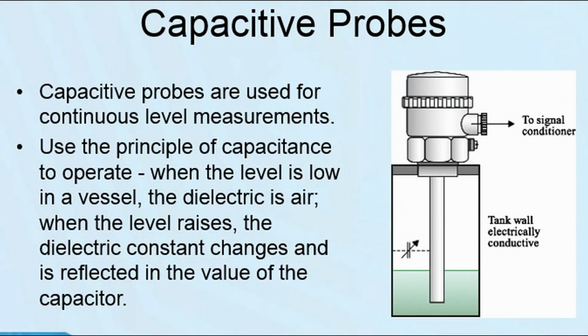A capacitive sensor works because the liquid that's being measured is also considered a dielectric, and if you have more liquid, then the dielectric is more and the capacitance goes up, and this gives an indication of the level. The capacitive sensor is invasive but indirect because you are really measuring capacitance. Then you have to build a circuit to convert that to indicate level.